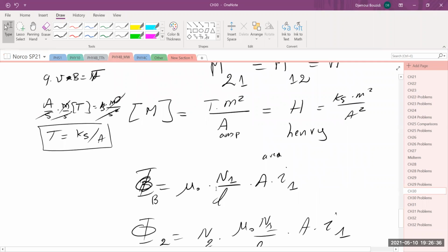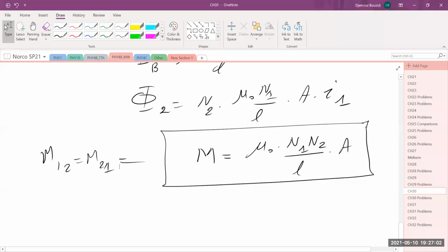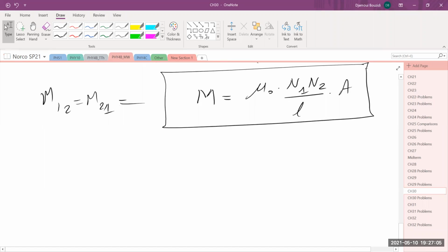And mutual inductance, as I was saying, if you're worried how it looks like on a circuit, I was showing you that. This is how it looks like. It's this material in here that is actually the wrap around these things. And that is actually self-inductance, which we'll need immediately. The self-inductance is just like the mutual inductance, but it's the wire wrapped up on itself, that's all, okay? So that is what we're going to introduce immediately, the concept of self-inductance. For self-inductance, anytime there is a wire that wraps, you have the same thing. So it can have a flux that changes with the current inside the wire itself.